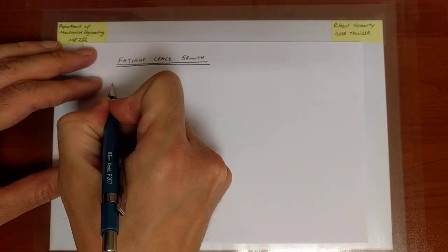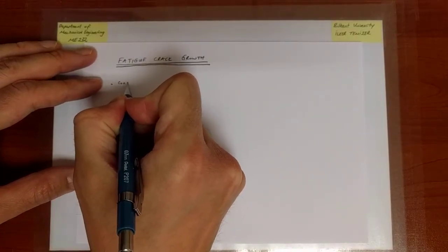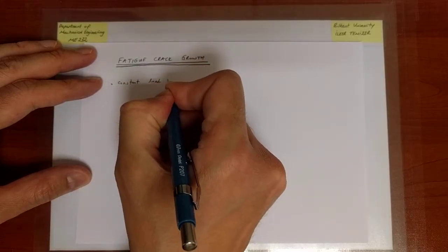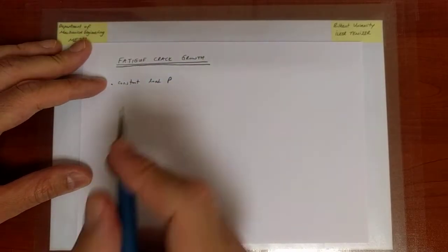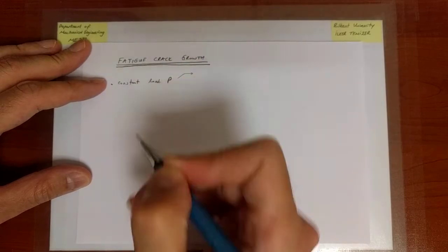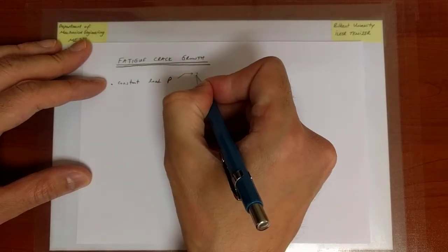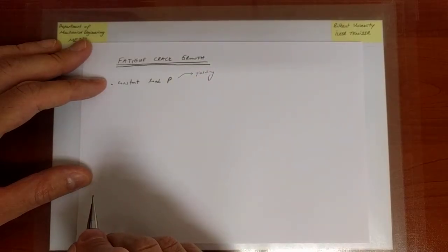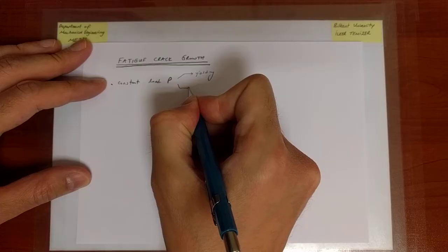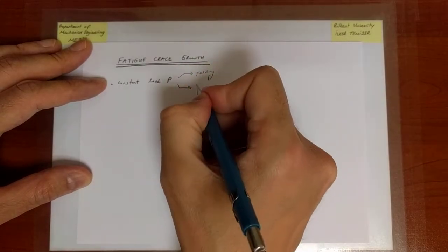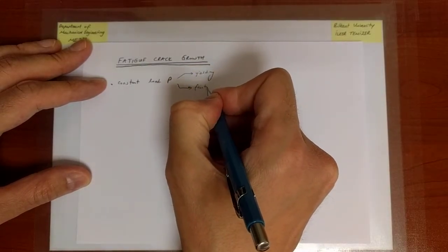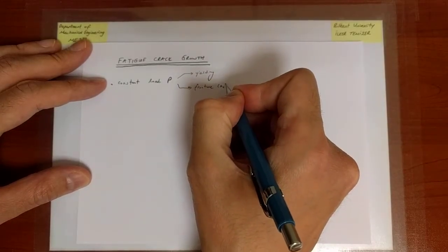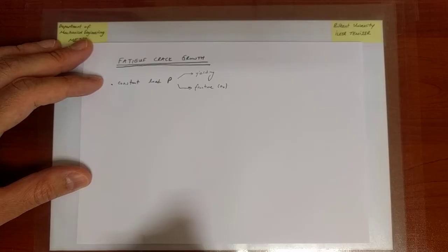So to summarize, essentially one observes experimentally that suppose you have a constant load, it could be tensile loading as well. Here I'm just writing P, which does indicate tensile loading. It could for sure yield. So those are the two failure issues that we are concerned with, or it could fracture, and with fracture there is going to be some associated critical crack size.